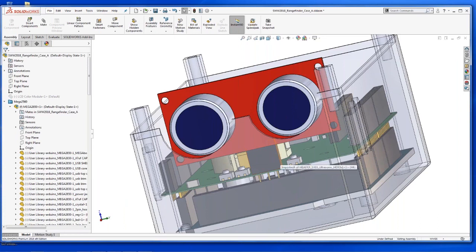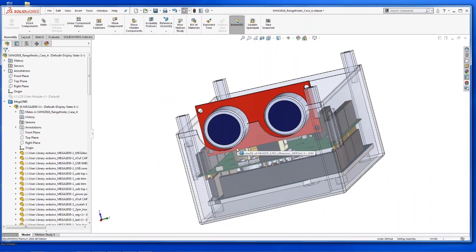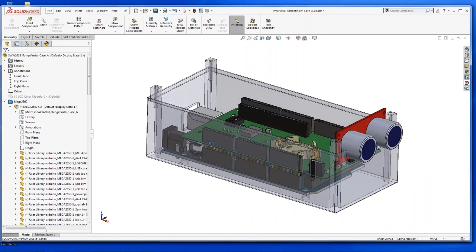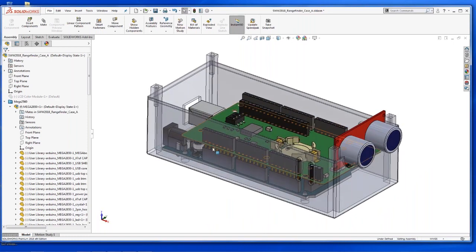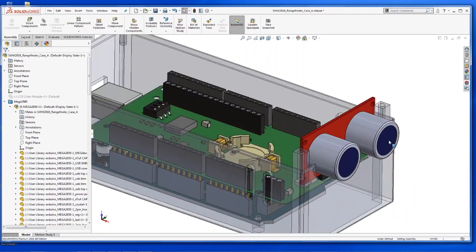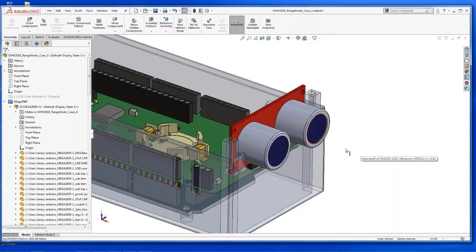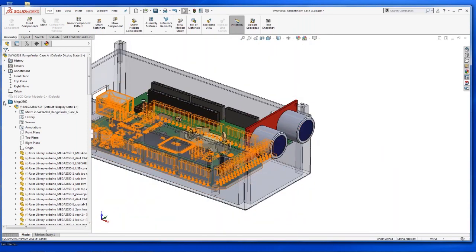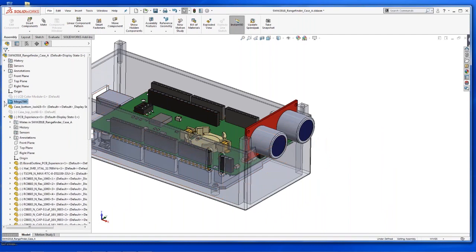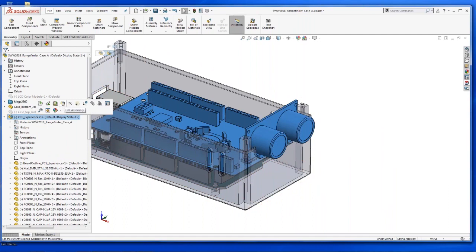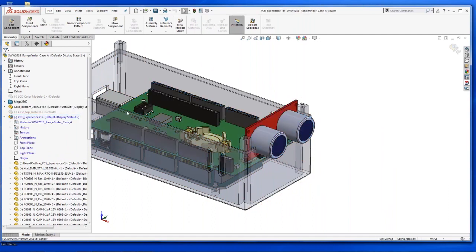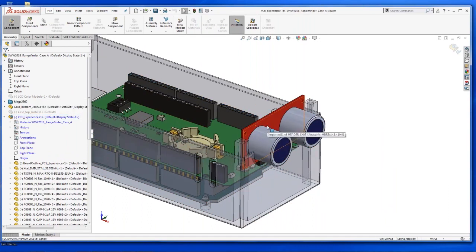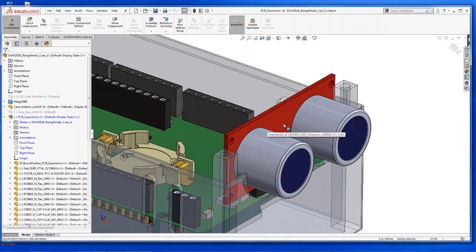So we can use SolidWorks evaluation tools and do an interference detection, and it will highlight this particular area. Now it takes a little bit of time in some instances, so because we're on the web, we're doing a quick demonstration. I'm just going to go ahead and edit the assembly and modify that component. Okay, so now we're in the edit mode for the main assembly.